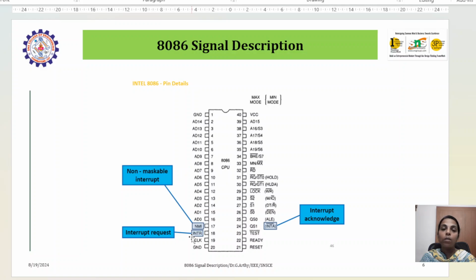At any cost, whatever kind of programming you are doing, whatever program is being executed, it doesn't bother about anything. If the battery is low, less than 5, immediately it will give a prompt that the battery is low, right? That is an interrupt which cannot be masked and which should not be masked. Those kinds of interrupts are known as non-maskable interrupts. There are other interrupts which are maskable interrupts too.